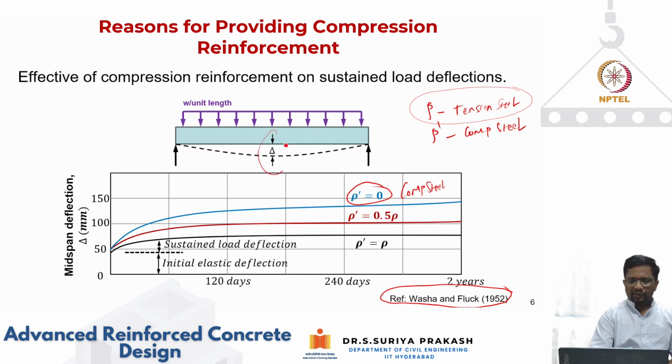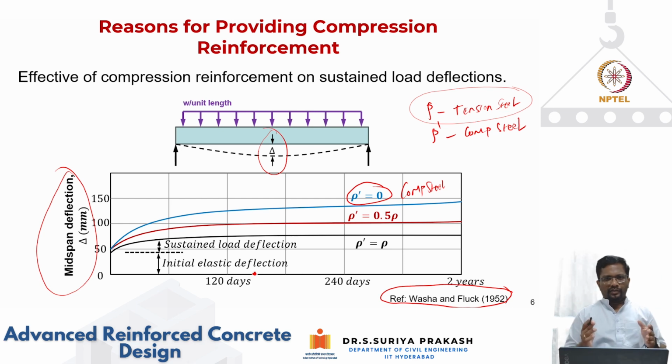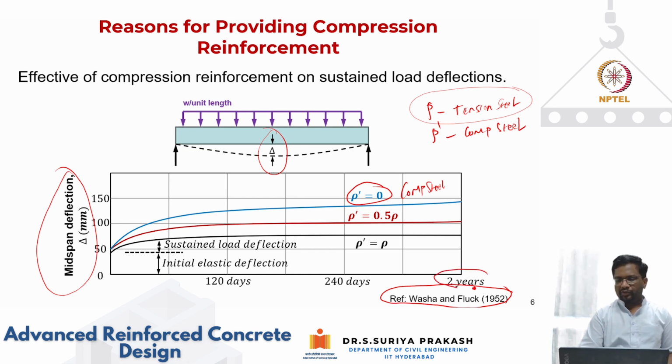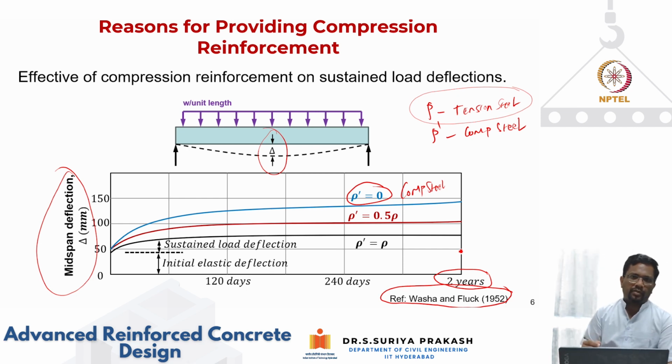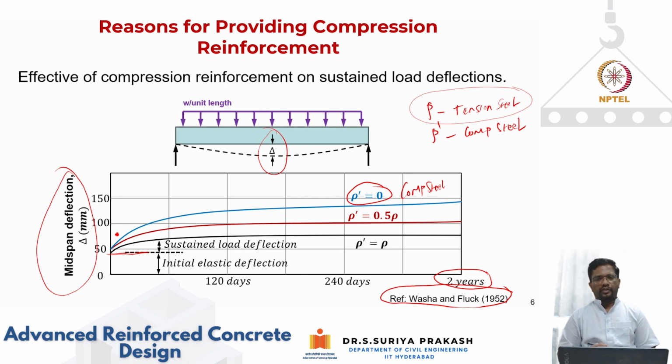We are plotting the midspan deflection on the y-axis, and on the x-axis we are measuring time. Let's say I start loading from day 0, and then I measure the deflection every 10 days or so, and they measured the deflection for almost up to 2 years. As soon as I start applying the load, of course, I'm going to have some initial deflection. Roughly it is about 50 mm.